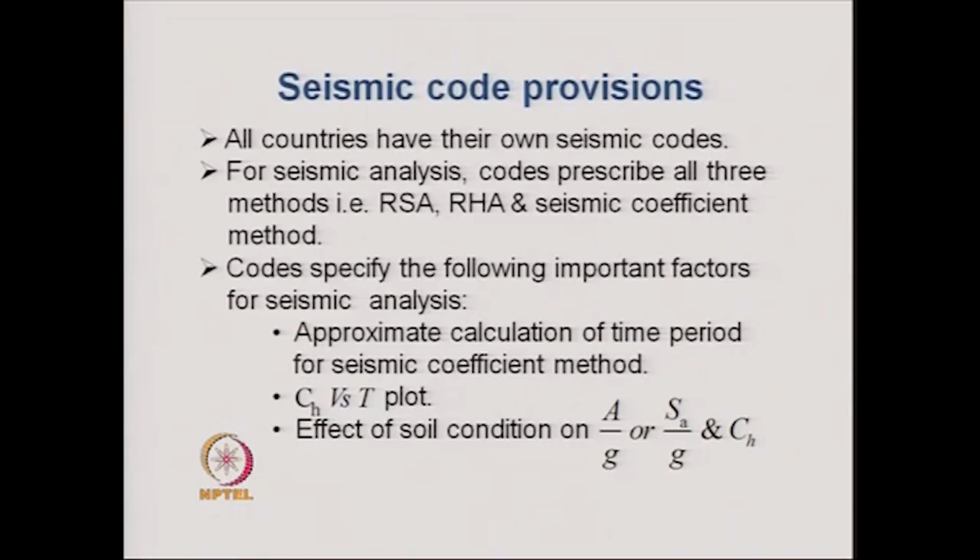The time history for which the structures are to be analyzed depends. The time history of the ground motion could be a site-specific time history of ground motion. It could be a time history of ground motion which has developed the maximum amount of damage in the past in that particular region, or one can construct a time history of ground motion for a given response spectrum or a given power spectral density function. All of them we have studied when we were discussing the inputs for ground motion. We have seen how one can construct a response spectrum compatible time history of ground motion or a power spectral density function compatible time history of ground motion.